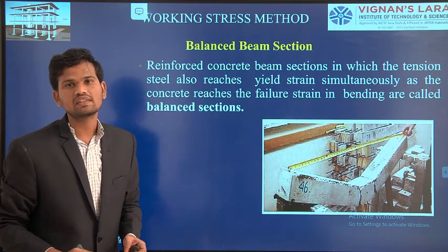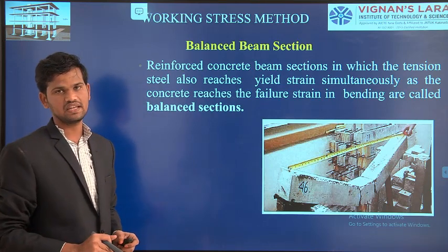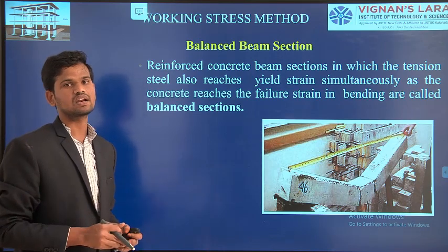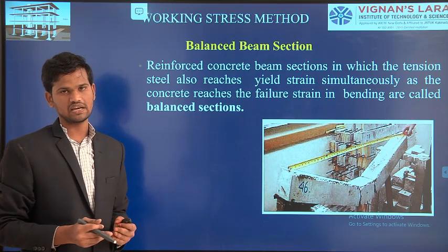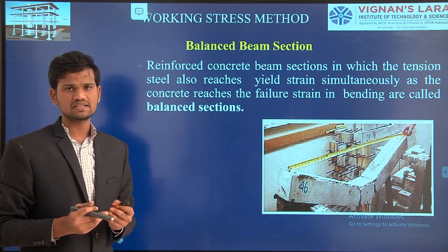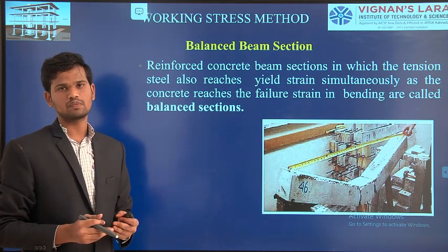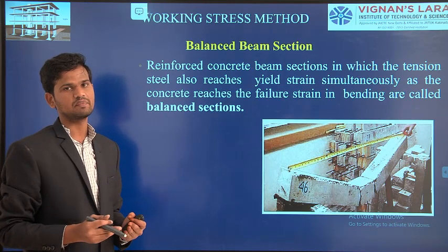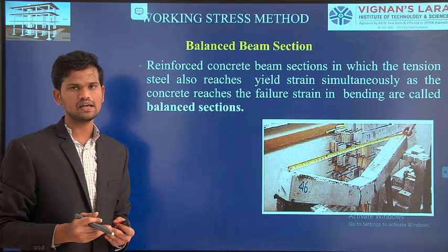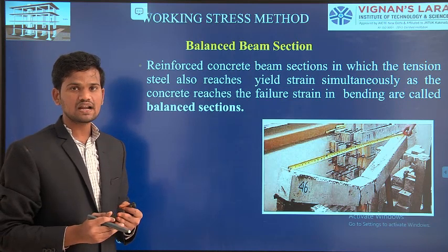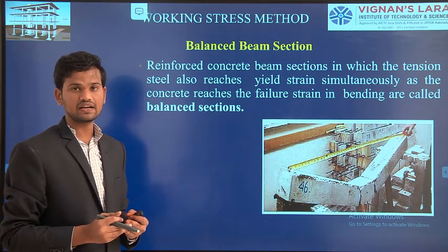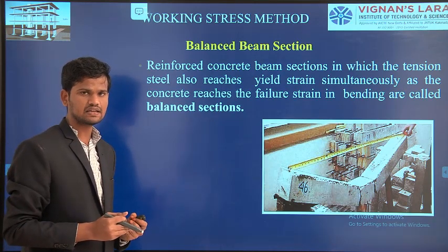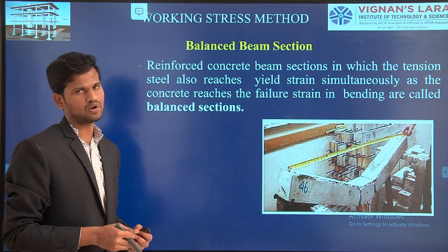And next we have the different types of sectional members for designing any concrete member. In structural design, the beams are classified as singly reinforced beam and doubly reinforced beam. Based on the loading condition, we have simply supported beam, cantilever beam, fixed beam, overhanging beam. Based on the supporting conditions we are dividing the beams, as well as based on design conditions. Those beams will be called a balanced section, under reinforced section, and over reinforced section.